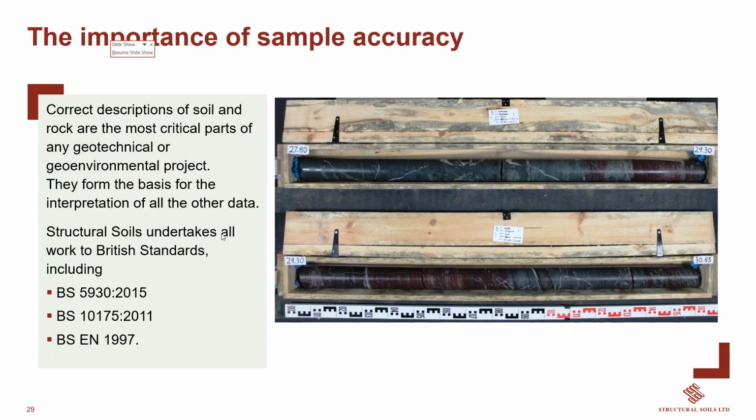We take a huge amount of care and attention when we come to the rock core that we bring out of the ground. We take photographs of it before we do any logging of it, so we get a true record as best we can from the ground, and we can always go back to that, and that forms part of our report.